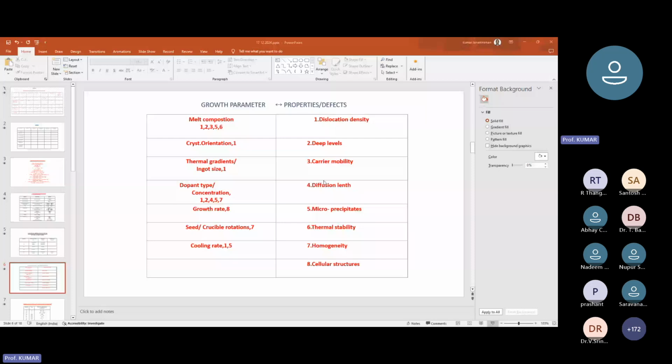Even in this case, you see, if I take silicon and use it as an N-type dopant, but if I use a quartz crucible, then it has 1 into 10 to the power minus 3 as a segregation coefficient, and 0.15 if I rotate the crucible very fast. Whereas if I take pyrolytic boron nitride, then it can have a segregation coefficient greater than 1, because this is not going to release any oxygen, and therefore most of the silicon will be distributed in the top layers of the grown crystal.